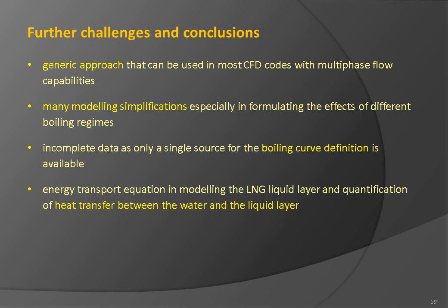The energy transport equation was not used in modeling the LNG liquid layer to avoid the definition of the heat transfer between the water and the liquid layer. Such definition would have to involve, or at least quantify, the effect of ice formation and its thickness, state of the surface, and any convective mixing.